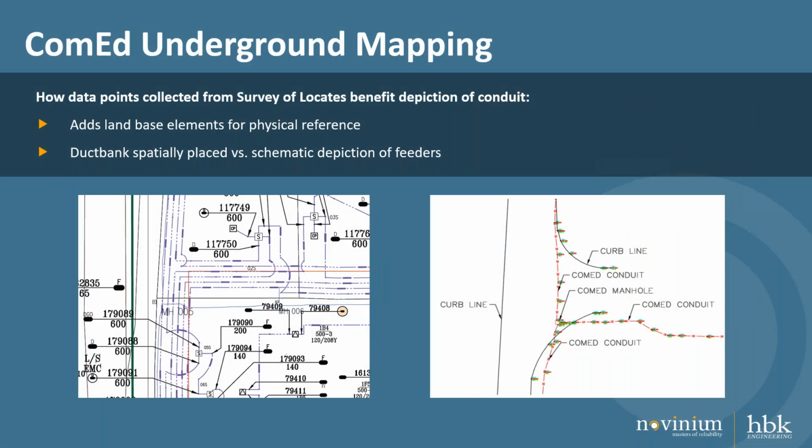As we looked at the approach we were developing to tackle this program, the decision we made as a team was to utilize the simplest and most basic methods of data collection of underground infrastructure. This simple, direct approach was to put locating and surveying crews in the field, accessing manholes and substations with the initial swipe at updated circuit maps, to tone, locate, paint, and survey the paint marks of the underground infrastructure from the bus position at the substation all the way to the upfeed location on an overhead distribution pole, or to the distribution cabinet or piece of equipment where the circuit terminated.